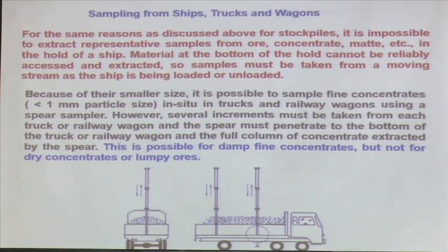So the best way is that when the truck is getting filled up or getting discharged, that time I should do that. Thumb rule, I would say that for coarse particles, for sampling, forget about the formula and all this. If you are not comfortable with that, make sure that for the coarsest particle in that population, you have selected at least 3000 particles.